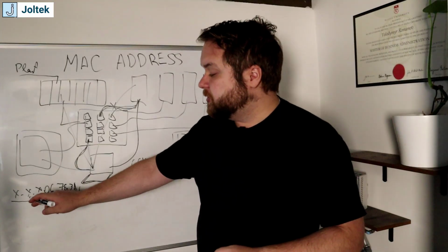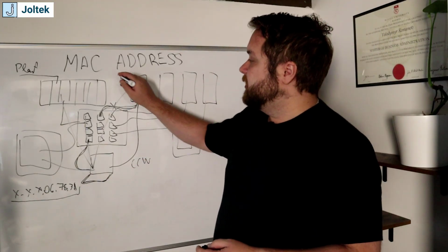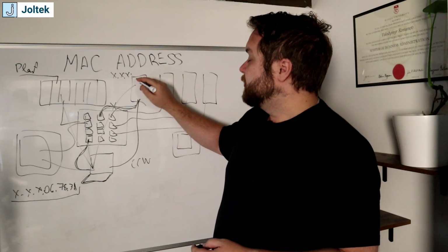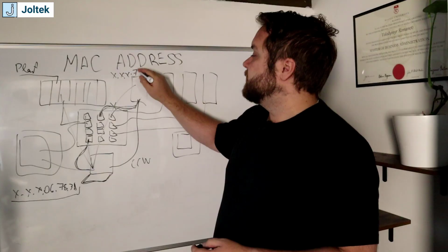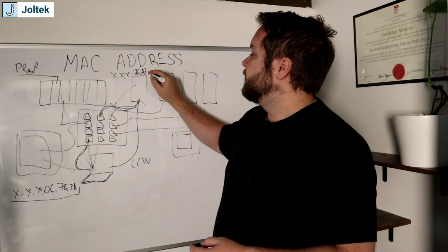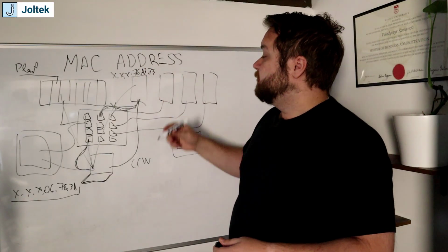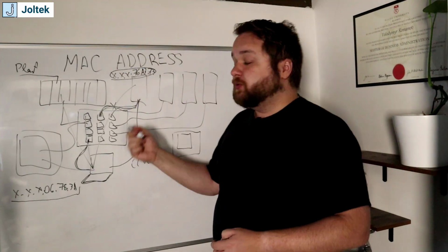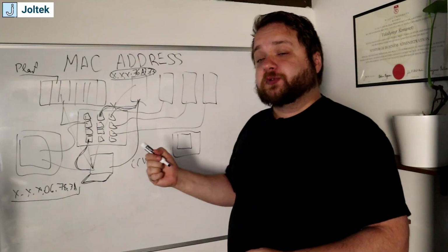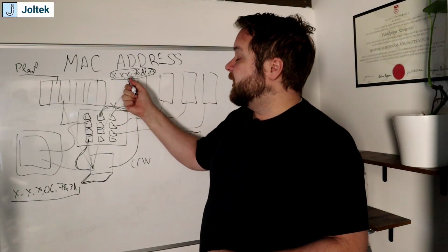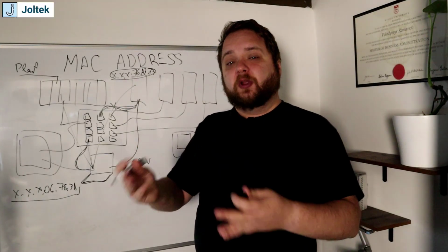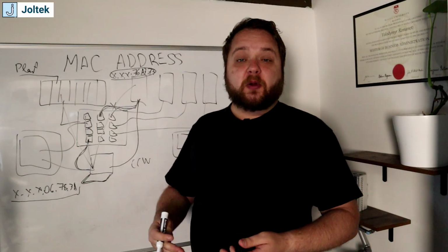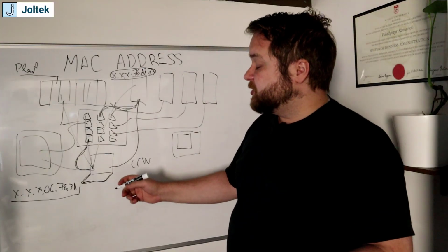As I've mentioned, each device is going to have a unique MAC address. So here, our drive is going to have, for example, the last 3 octets as 76.A3.73. And so you're going to be able to write this down, and as you connect to that device, I always want you to double check that the MAC address of the device in the real world matches what you're pushing your changes to from your specific machine.